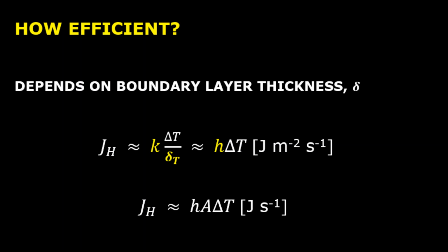As you know, the effective convective heat transfer coefficient, H, depends on the physical properties of the fluid and the physical situation, let's say the fluid velocity. So the convective heat transfer coefficient is not a property of the fluid. It is usually obtained in an empirical way, conducting different experiments, and the value of H will depend on the variables influencing the convection: surface geometry, nature of the fluid motion, properties of the fluid, bulk fluid velocity. So you will have to use an appropriate empirical correlation to get the value of this H.